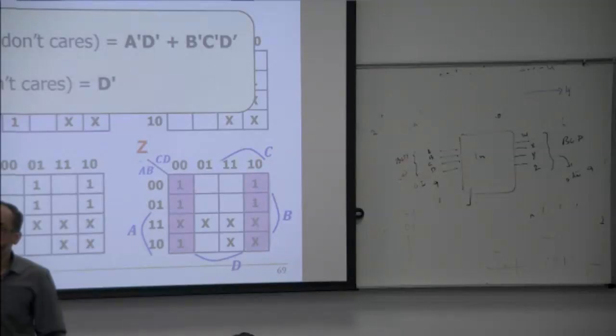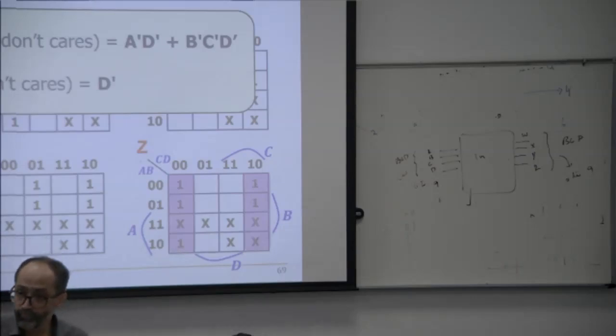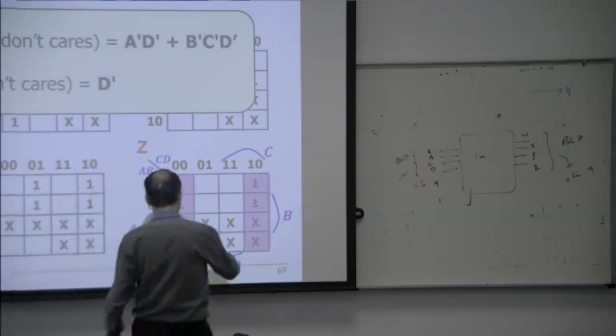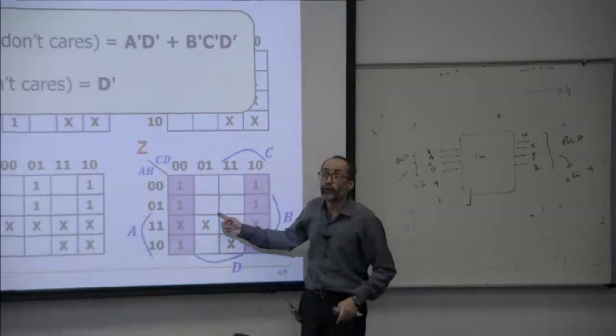Using the don't cares in the essential prime implicants, doesn't it mean that the don't care values are 1? No, it doesn't. You should not include all of the X in the prime implicants. Wherever we include X in our boxes, it will mean that the X is 1 since we are constraining. No, you don't, because if you look here, these 3 are not covered.